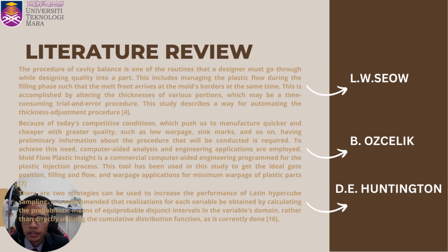Moldflow Plastic Insight is a commercial computer-aided engineering program for the plastic injection process. This tool has been used in this study to get the ideal gate position, filling, and flow, and the warpage application for minimum warpage of plastic parts.